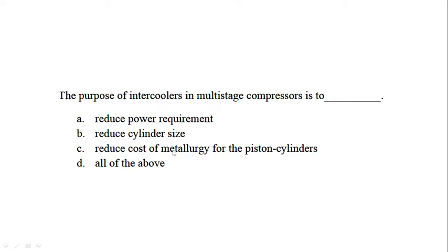Then can you tell how the usage of a cooler will help to reduce the cost of material of construction of the piston and cylinder? Just before that, what will be the condition? If we do interstage cooling, will the process be adiabatic or isothermal?